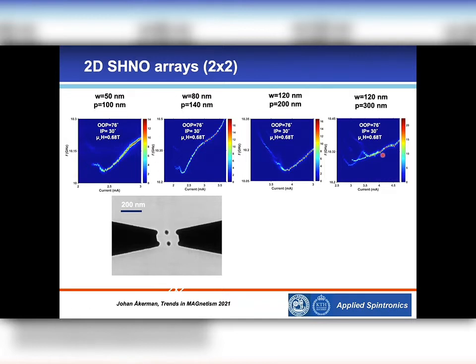What is slightly different is that the power goes up with width. So you can see here peak power is 14 dB over our noise level for the smallest ones and about 22 dB over for the biggest ones. And that is well known for these constrictions, that the bigger constriction you have, the better signal properties and the greater power you have, most likely because the mode volume is larger and less disturbed by thermal energy.